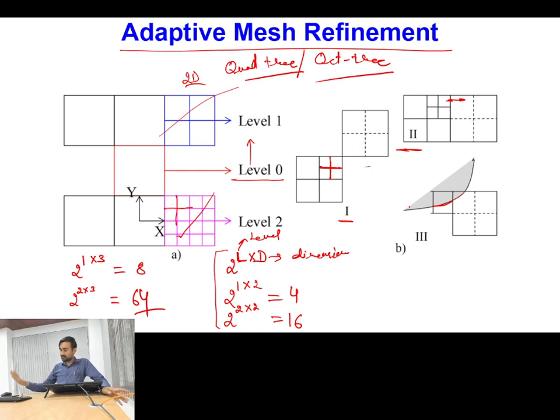Okay, so this is about the adaptive mesh, and adaptive mesh is a need for multi-phase flow problems, because if you go for a complex multi-phase flow problem where your interface is breaking into micron sized droplets, you cannot create micron sized grid structure everywhere in a larger domain. Okay, so then your computational cost will be excessive. So that's why we create fine meshes only in the zone where I have micron sized droplets, and away from that I can keep on decreasing the level and go with a coarser mesh structure. Okay.